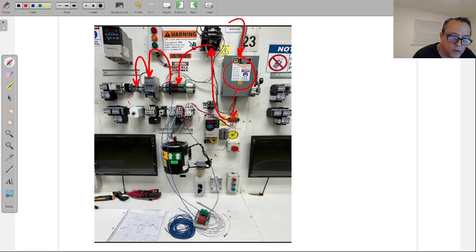So if you're ever, and you will, work on the 24 volt DC power supply side, I meant to say, and you don't have power here, then again, you got to work your way. You're looking for a fuse somewhere here. You're checking out that power supply. Usually we don't damage that, but in the real world, it can get damaged. Going over to the fuse here, seeing if that's doing well, working your way back.